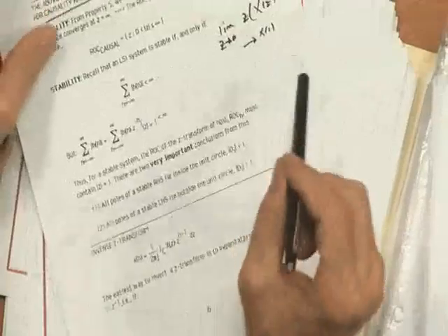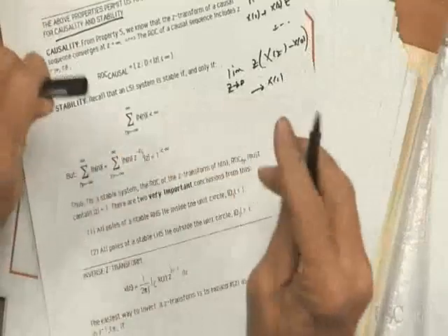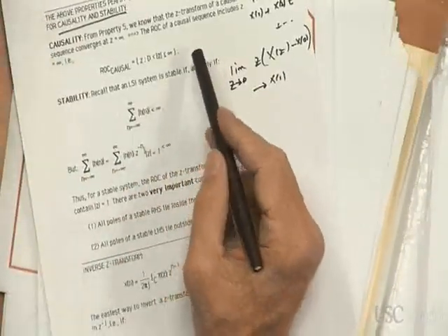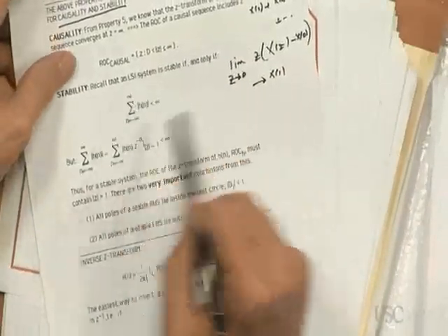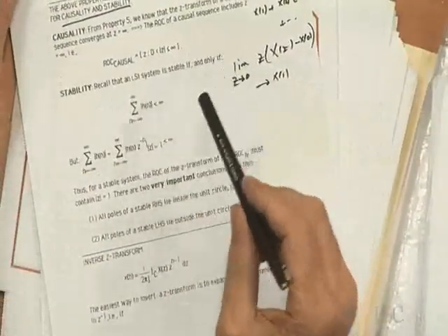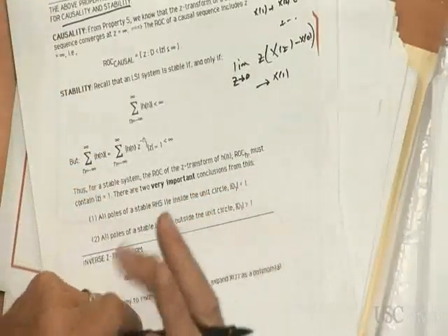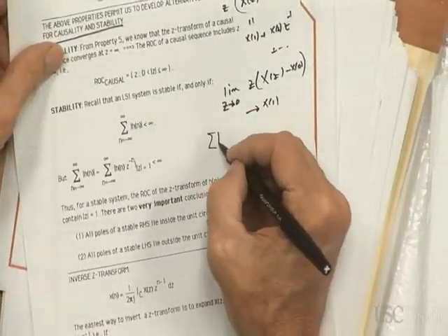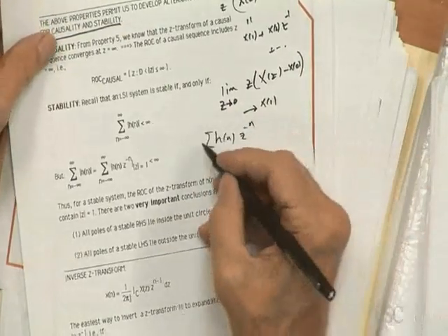But here's another way. This is very interesting. This is stability. Now we know that if we have a linear shift-invariant system, the way to test for stability is to look at the impulse response, and if the impulse response is absolutely summable, then the system is stable. Well, here's a little trick. If you can use the z transform, and the trick is, what is this? Summation of h of n, z to the minus n. What is that? That is obviously